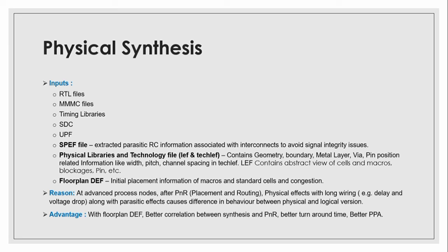Now the first round of physical design we will perform only till floor planning. We'll have a floor plan, place all the macros, blockages, all the IO ports, pins, and the basic physical cells, so basically the initial placement. Depending on the design, some companies prefer to have the initial placement information in a DEF file, and some like to have the final placement of cells, generate a DEF file, and then give that file to the synthesis tool. But both are okay.